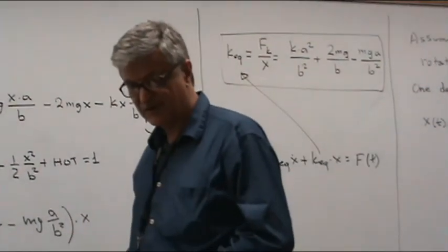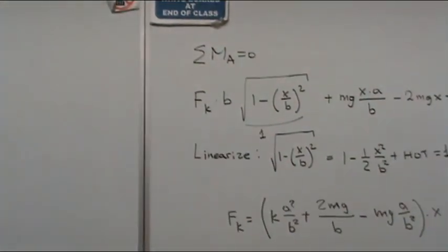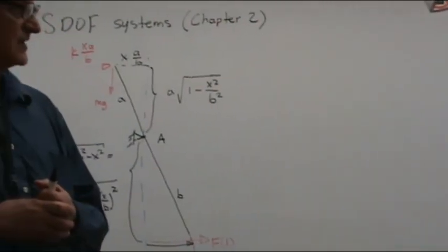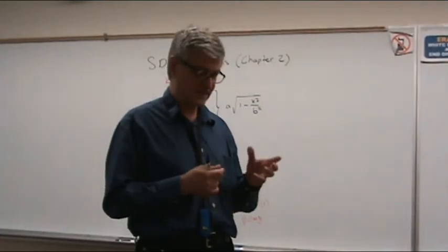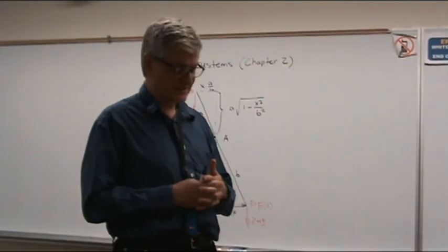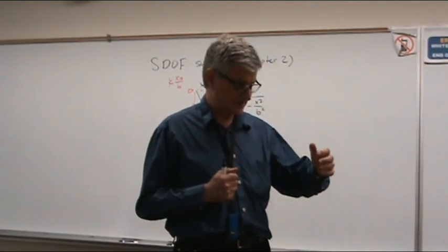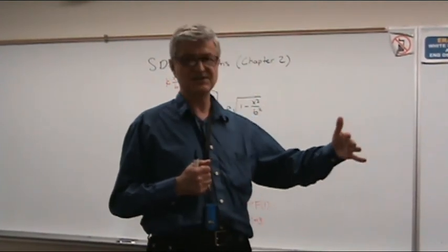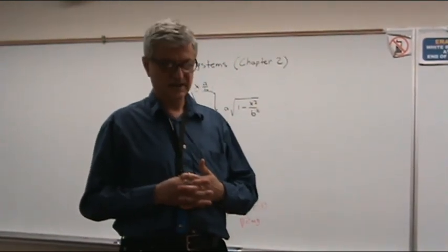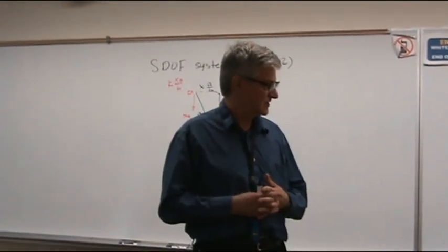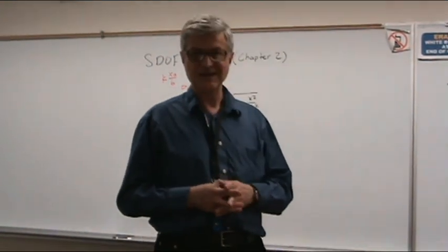Okay, so today we talked about 1 degree of freedom systems. We said that there are 3 methods that you can derive the equations of motion. The 2 actually are pretty similar. The unit displacement method, where you consider unit displacement and you find the force that is required to produce this result. The second one is just Newton's law. And the third one involves energy principles. Okay, let's stop here.